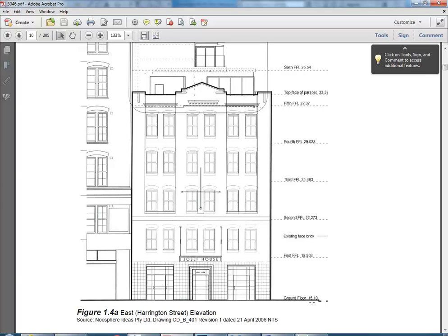If you can, it's good, yeah. If you're close to sea level, then just work with absolute levels, which is what I'm going to do here. Yeah, relatively, because it's in the city and it's not that high above the actual sea. Often you'll have even lower levels than this. I've worked with 5 and 10 above sea level over in Bondi and places like that. But often, yeah, well, it's easy. If you're working with AHD, then you don't have to tell anyone that I'm setting out a certain distance above AHD. I'll just know that it's this distance, that's your absolute level above sea level or above AHD.